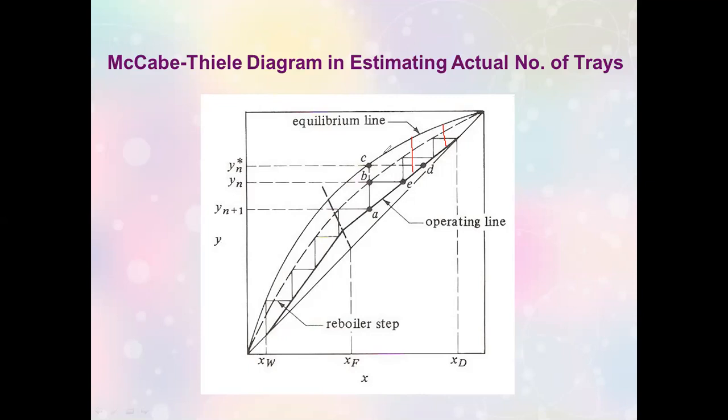So I have another straight line here, another straight line here. Take note, I'm starting from the curve down to the operating line. In the upper part, of course, down to the enriching section operating line. In here, to the stripping section operating line. As I said, the more vertical lines you have, the better. Okay? You have drawn vertical lines already.